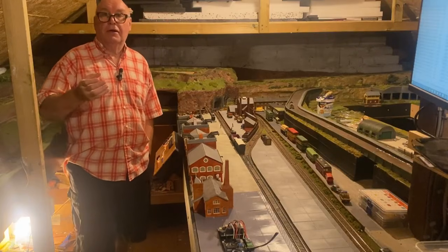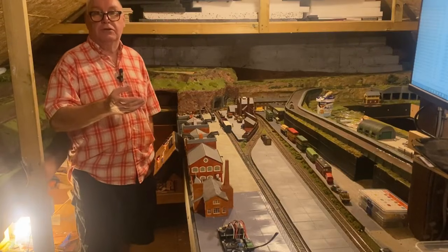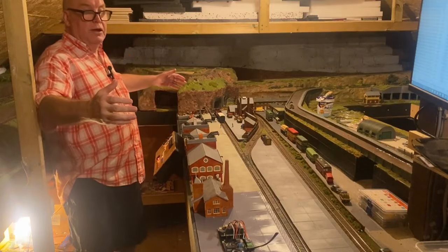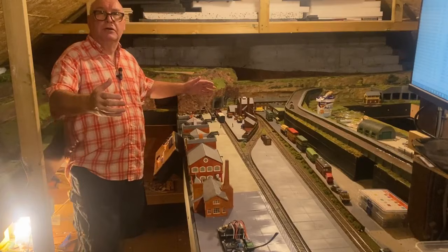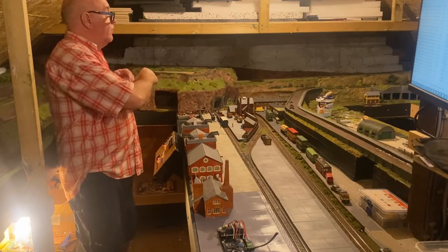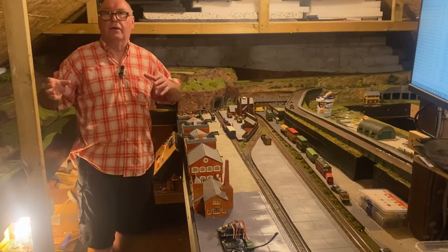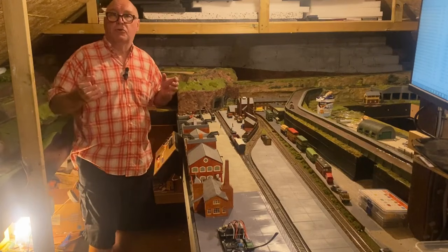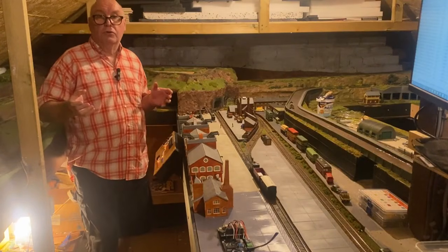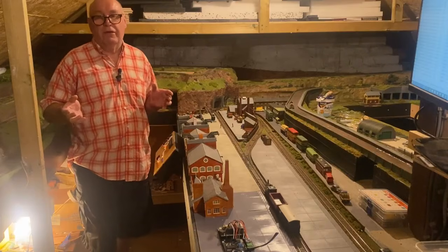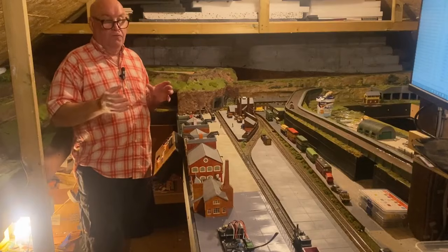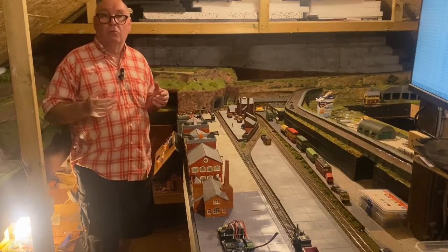So you might say to me, well, John, you could do all this with DCC-EX, and yes, you could. This section is only 8 foot by 4 foot, so an I2C bus interface for all this would work. But once you start spreading it out around the whole loft or slightly bigger, I2C can sometimes cause issues. Yes, we can extend it. Previously, this was all done using JMRI and the RS485 bus. Obviously, I've learned the new technique of using a CAN bus. Hopefully, this now will work the way I want it to.